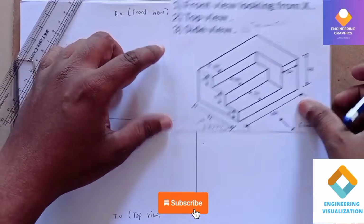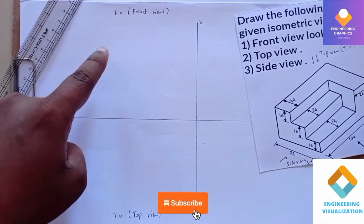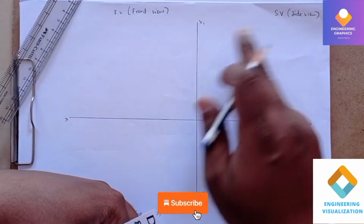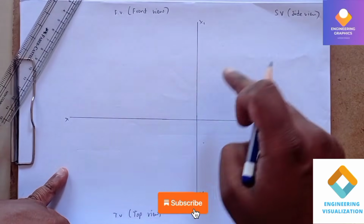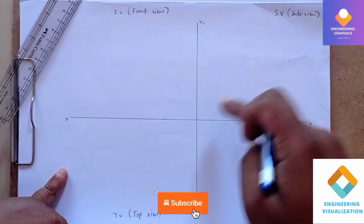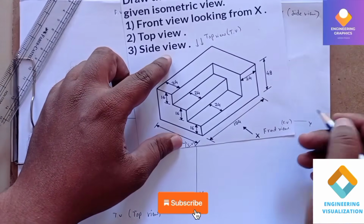You can analyze from the front view which faces are visible here. I'll be constructing the front view, top view and the side view. You can see the front view and side view are always adjacent to each other, and the top view and front view will be in a vertical collinear line. In order to connect the top view with the side view, we draw a 45-degree line.